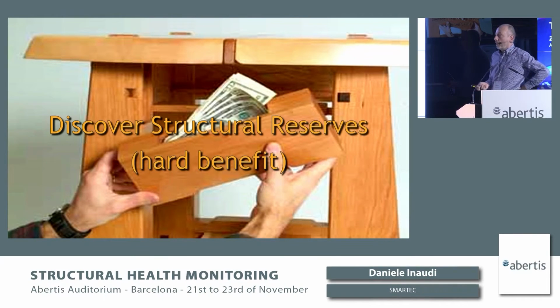So, for example, we had several cases of structures, bridges in particular, that didn't look very good in terms of visual inspection. But once they were instrumented and when the recorded performance was compared with the calculation and the model was updated, they found out that the structure was in much better condition than expected. In particular, because the quality of material was better than assumed.